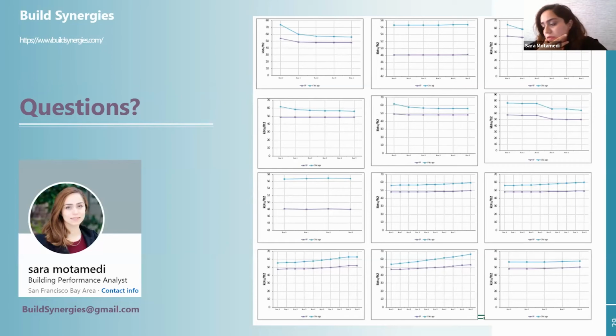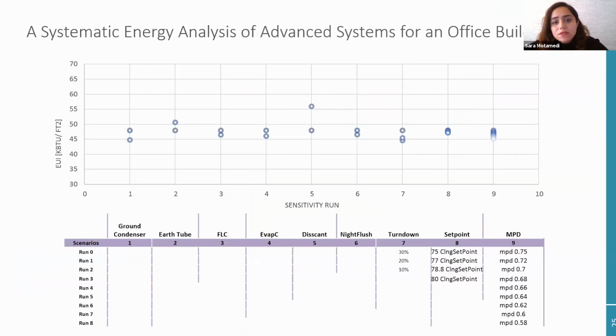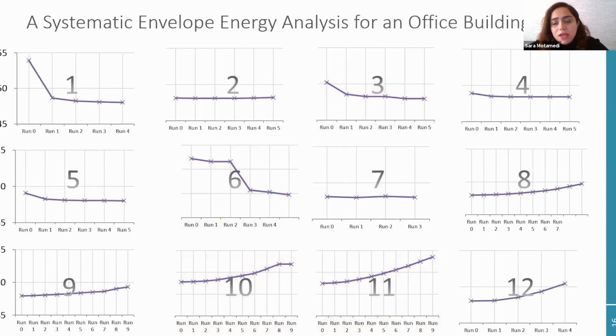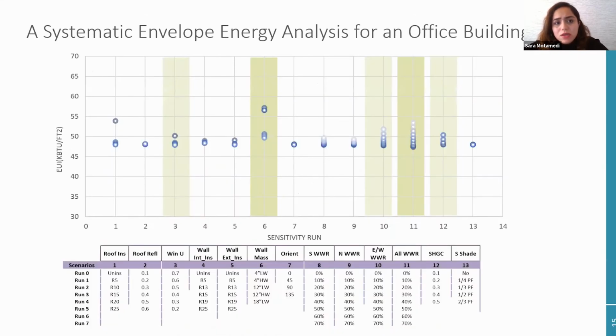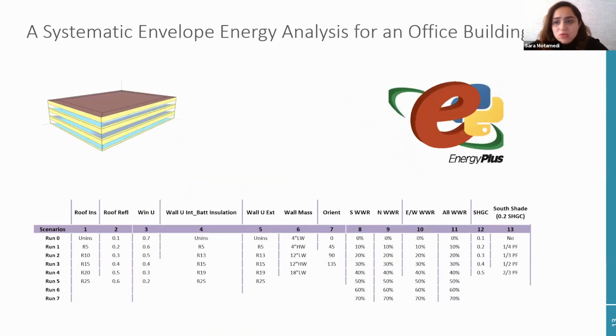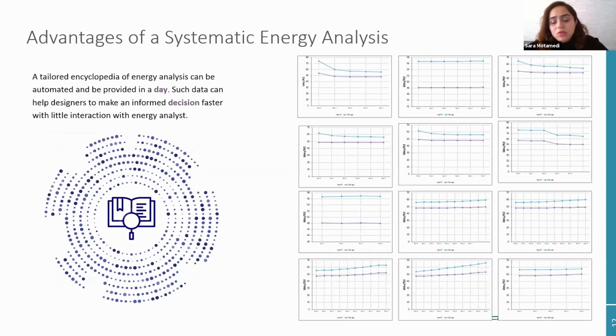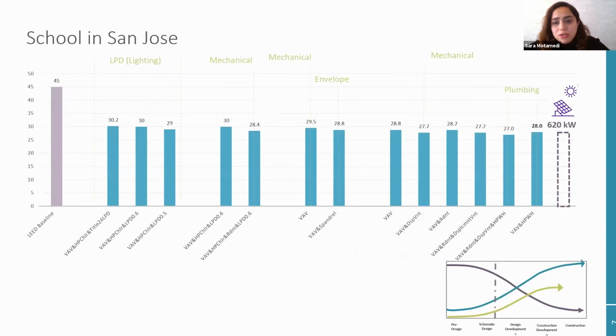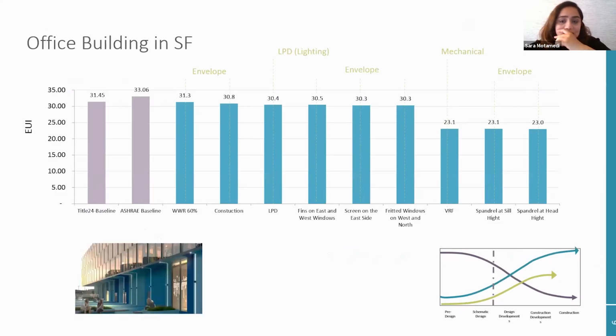I can give you two examples, one successful and one not successful. The one that I actually gave, the San Francisco office building, the VRF system was the one that they considered. So that was a success story for us. They wanted VAV. Most projects want VAV because the contractors are more comfortable applying VAV in an office building or in a school, because they are more familiar with how the system works, how the maintenance works. But if you have new buildings, you can offer a VRF system and be more energy efficient. So for this client, it just worked.